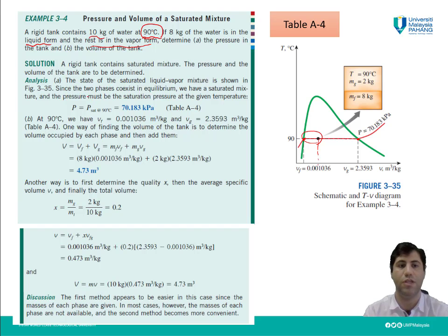First, because it is mentioned, we need to find the pressure in the tank. So since the two phases coexist in equilibrium, we have a saturated mixture, and pressure must be the saturation pressure at the given temperature.